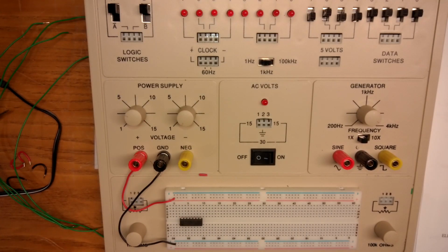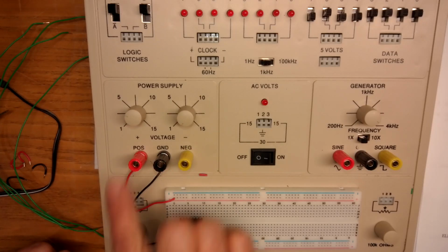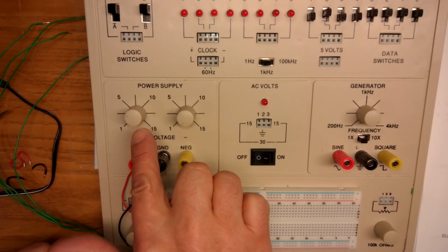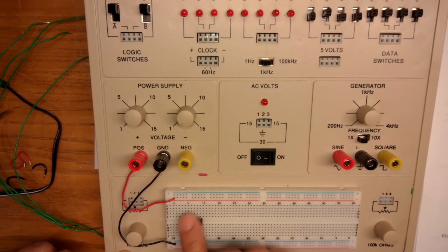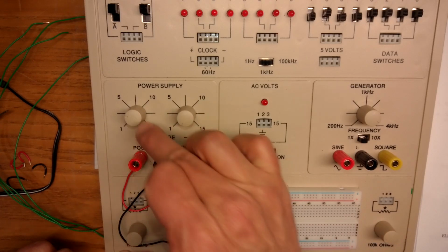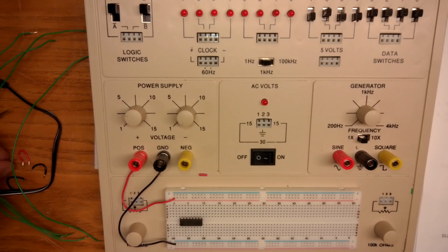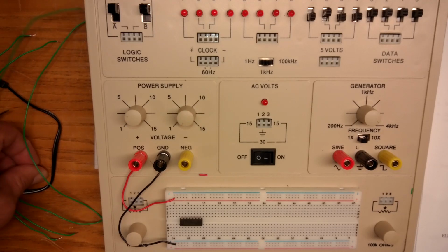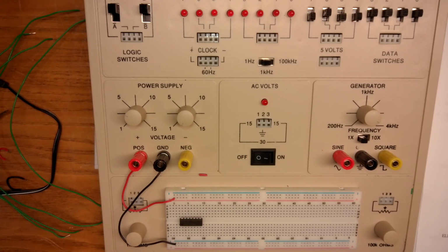So on the breadboard, or on the trainer, I've gone ahead and put power. I put ground. I put my 7400 chip down. Okay, I've gone ahead and set voltage. I'm going to remind you, check this closely. You don't want to run voltage in here if it's set up at like 15 volts. When I first built this, it had been left at 15 from the previous lab I had recorded. I just turned it all the way down and then measured it with the multimeter and set voltage. So I'm already set at 5. I'll come in and just put ground, so I have ground.